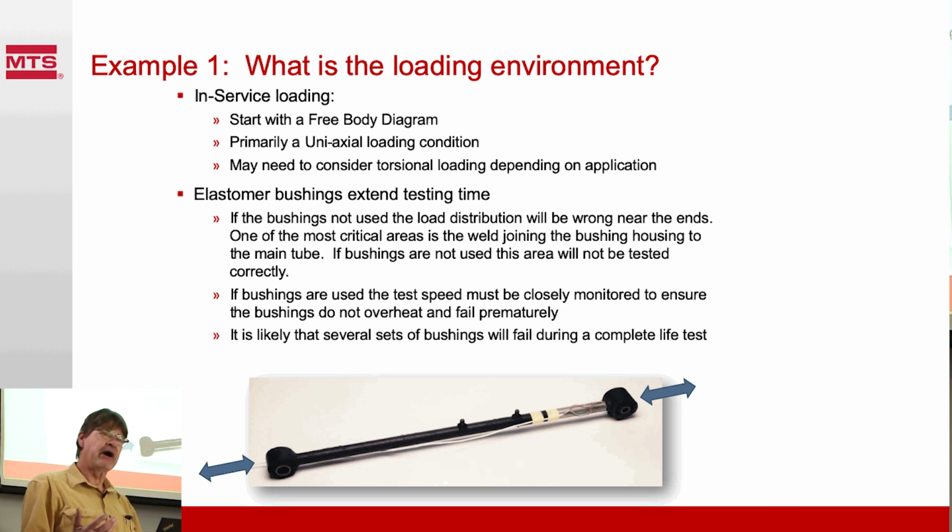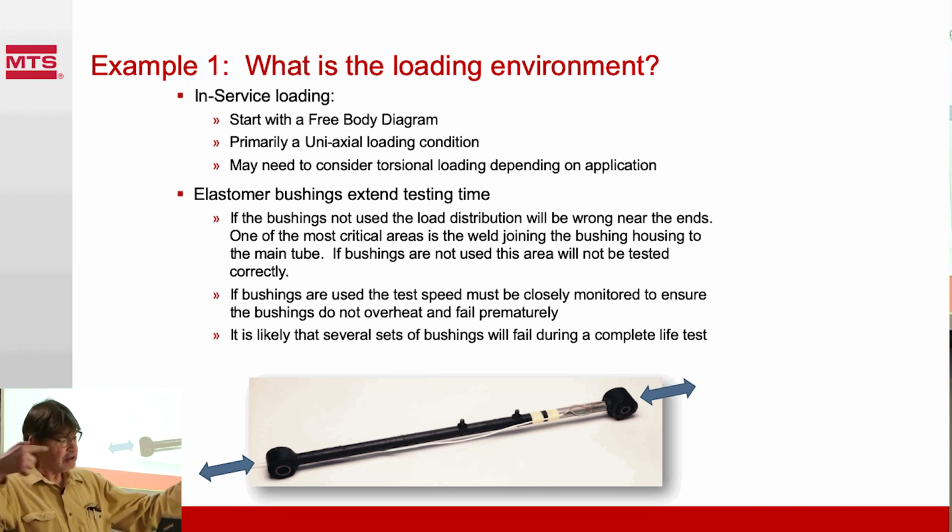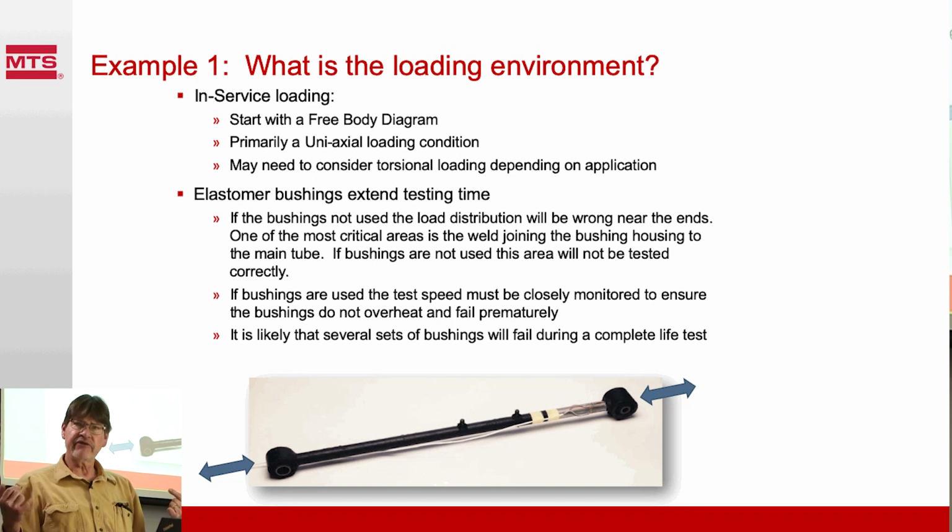We want to start with a free body diagram. As it says here, we're going to put tension compression loads on the strut. That's what we think is our primary damage. We're going to use a uniaxial loading, and we may consider torsional loading depending on the details, but we'll see. We'd like to avoid that. It adds complexity to the test, but we'll know more after we acquire some data.